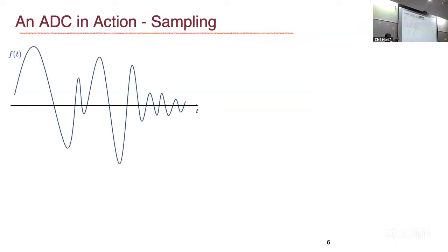Let's talk about sampling. So here is a signal f of t, where t is time. So this is an analog signal, is it? Okay, now what do you mean by sampling? Discretization in time. So instead of having this entire signal everywhere, we measure it typically at a uniform rate. Every TS interval we take its value and those values are represented as f of nTS, where n is an integer. We are going from time minus infinity to infinity, everything. On paper, in theory, everything is possible. Yes, fine. So this is the sampling.